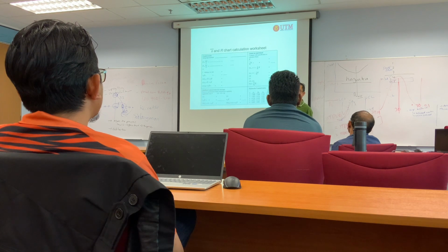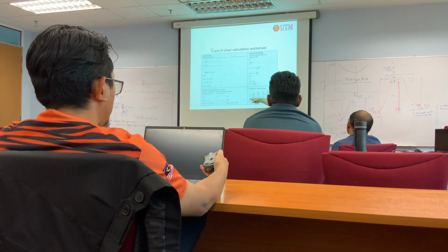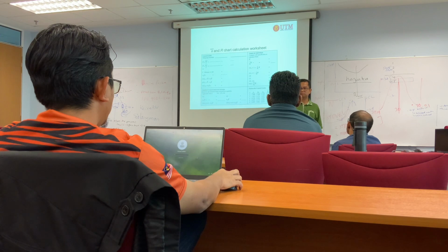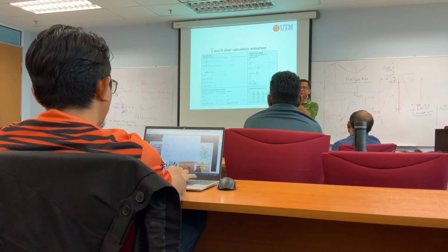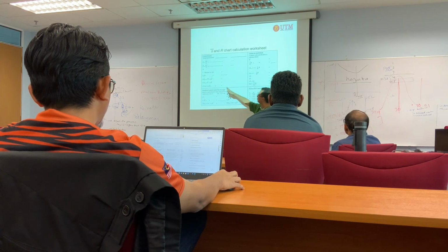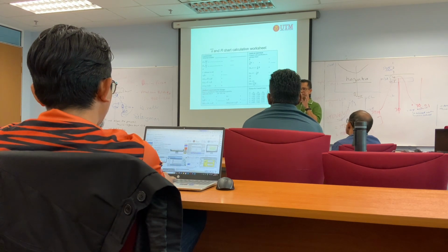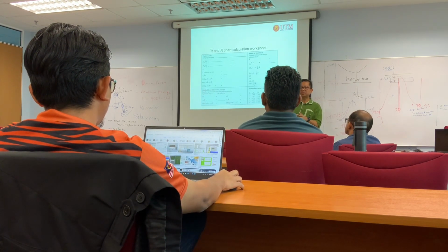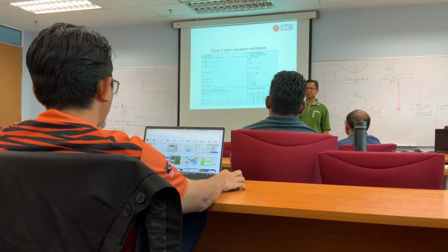Instead of using the statistic value, for example, this table A2 depends on how many samples we have for each subgroup. So for your case, if you want to know the distance for the upper limit, for each testing, how many samples do you have? Let's say 3. So your A2 will be 1.023. Then you multiply by your range, R bar, the average of the range. So we assume that is what we call 3 sigma. Maybe it's not that accurate, but it's acceptable by the industry. Okay, do you understand or not?